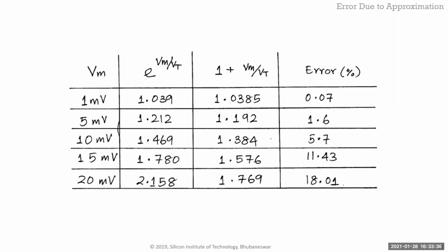So this is another way of showing you. Like that question you asked me, how much delta V in can I use till the model is valid? My answer will be, how much error can you tolerate? Take a simple diode equation, ID equals IS times e to the power VD over VT. I just took the exponential term because I'm looking at the error percentage. I don't care about the IS term.